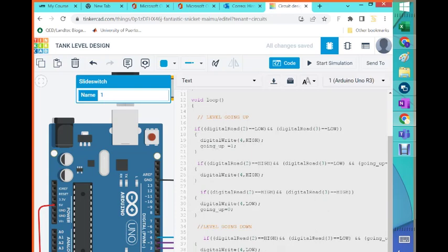But now check this if, and this if. I'm testing 3 situations on each one, and there is a situation that is common to both sides, to going up and to going down. They are common, and we have to make a difference why and when we're going to shut the pump off, and it's when we are in the down position. So use another variable to identify that condition based on code. I'm not adding anything else to the system to let it know that it's going up or going down. It's just based on the switches' position right now.